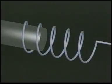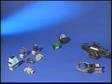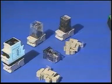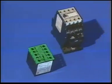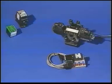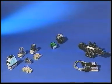We will take a close look at this specific effect in the section on solenoid valves. The magnetic effect of current is the form of electrical energy most often encountered in electropneumatics and electrohydraulics, in relays, contactors, and solenoid valves. In contrast to resistive loads, these are called inductive loads. The electric motor also belongs to this category.